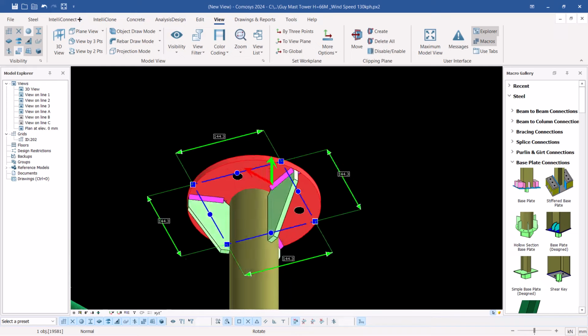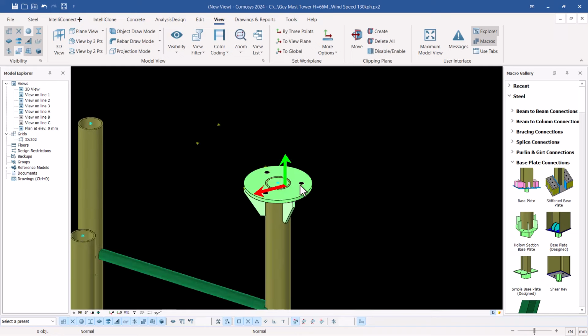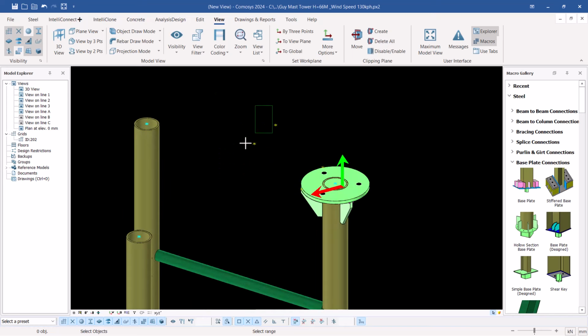So if I turn that around like that, I'll be able to have my flange right on the top, right there, like that. So what I'm going to do, I can either create a weld between these two, but there's no need. What I'm going to do now is just to populate this to the rest. So if I select that, then take my XYZ plane to a default by clicking the G there to take it to a global position.